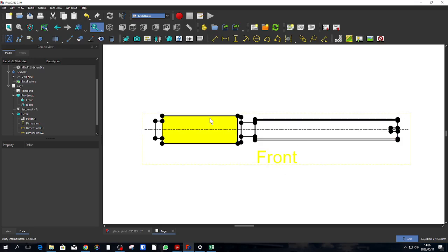All right, so the first thing we do is we define our datum, our primary datum. And this diameter over here of this cylinder pivot is very important. And it's a nice long length. So it's an ideal candidate to define as primary datum.